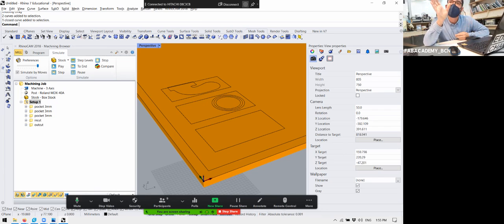But at some point, when we're cutting like this, it makes a little high noise. For example, in the corner, the speed is not enough, because when the machine is getting to the corner it decelerates to turn. That means maybe the average speed is too low. We could increase it a little bit, or we can take the corner with a different consideration. Or instead of cutting faster, we can cut deeper. There are little tweaks that you can always play with, touching the values. And most of the time you can define these things by the noise.